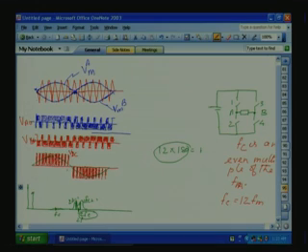These types of waveforms are called unipolar waveforms. Unipolar means one side it is going positive, the other side it is negative. The shape is such because, compared to the earlier one, FC is cancelled. So what is the advantage? We can use this for UPS applications. The filter's cutoff frequency has to be designed around 2FC, so the filter size requirement can be reduced. This way, by appropriately phase shifting the sine-triangle carriers and appropriately choosing the triangle carrier frequency, we can control the harmonics in many ways.